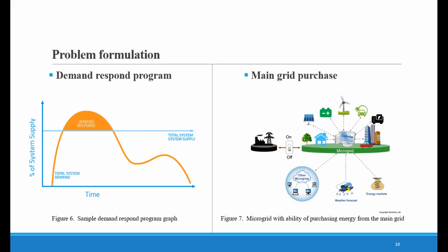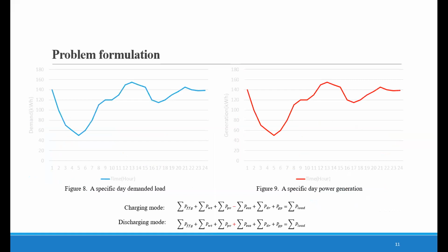Depending on the amount and the cost of produced energy by distributed energy resources inside the microgrid, in some periods, purchasing power from the main grid leads the system to be economic and reliable. The cost of the main grid purchase is calculated considering the price of the energy per hour and abonnement cost. The summation of the total supplied power to the microgrid must be equal to the total load in all time series and also be as economic as possible. Therefore, the cost function of energy storage system, demand response program, and all other suppliers should be considered to obtain the economic dispatch using optimization methods.